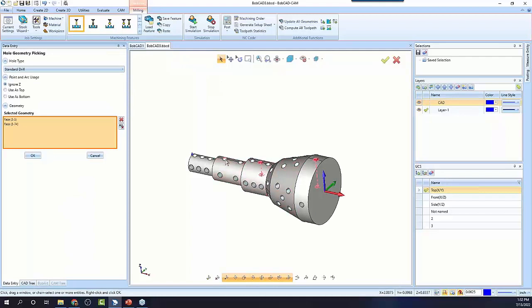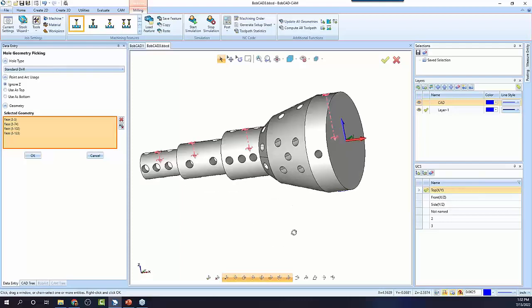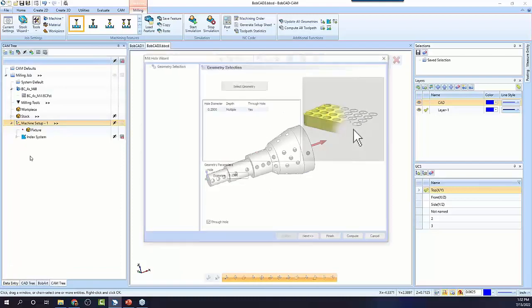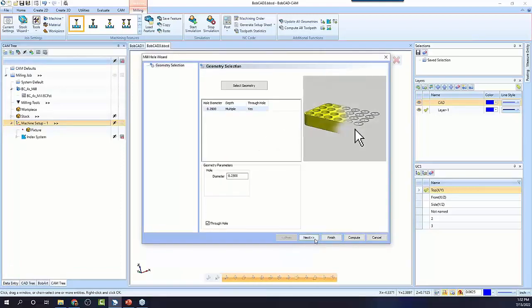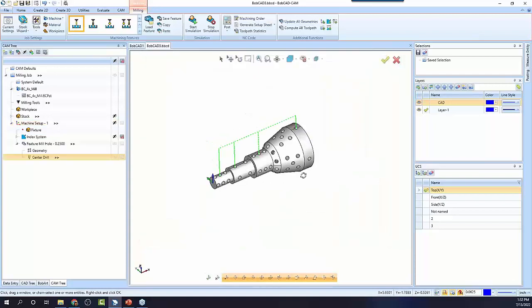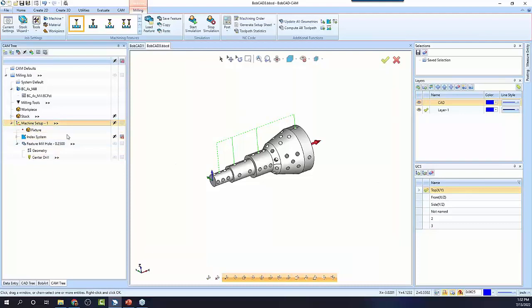Now, the holes can start and stop at different Z levels because we do grouping, okay? And using this grouping, we could select those holes. It's going to read all the hole sizes, and it's going to read the diameters. I'm just going to process this, and you can see how even not in an index system, if the holes align with Z, you can program them, okay?